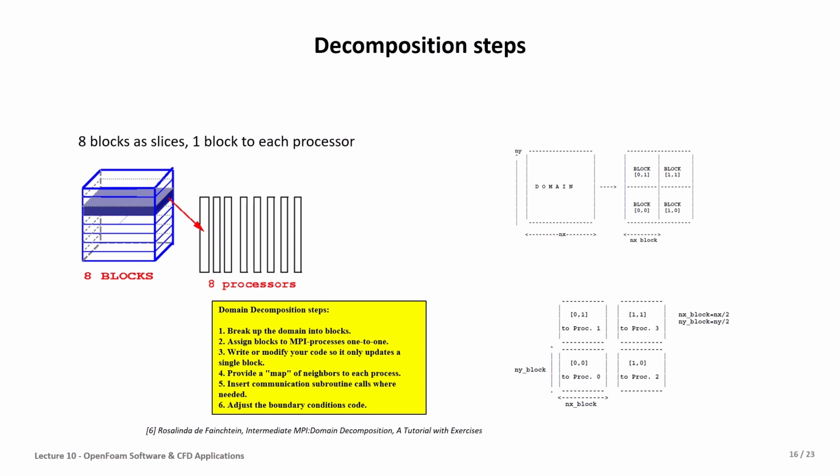This step needs to be done when we are using MPI, and we also need to mention that in OpenFOAM, this decomposition setup can be done from the decomposition block, and we can connect this decomposition to the MPI processor via setup.